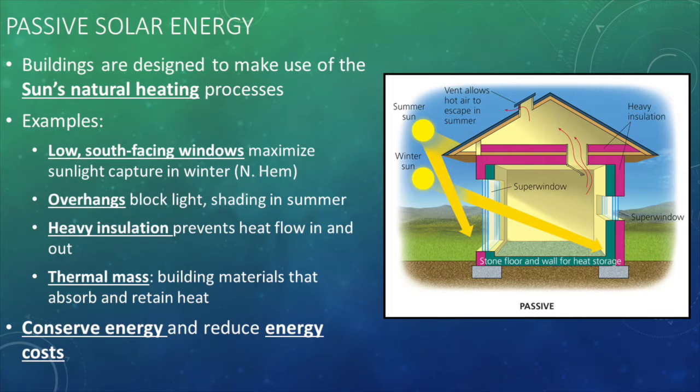For thousands of years, people have built and oriented their homes to make use of the sun's energy. Passive solar energy systems make direct use of sunlight to heat a building. Since the path of the sun is predictable, a building can be positioned to maximize its utilization of the sun's energy. In the northern hemisphere, for example, windows placed along the south side of the building will allow sunlight to enter year-round and heat the interior.